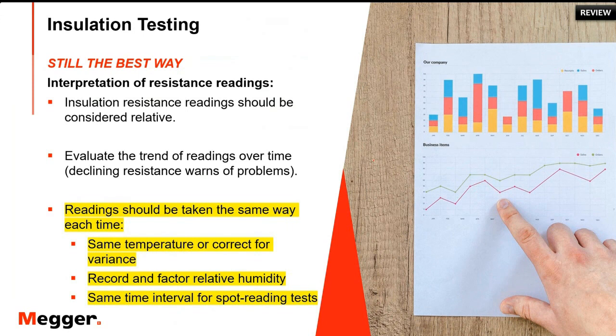So normally, when we talk of insulation resistance, we are correcting it to 40 degrees Celsius. Because remember, resistance has a relation with temperature. Meaning to say, as the temperature changes, the resistance changes as well. So you cannot compare values at different temperatures. You must have a reference temperature. And normally, when we have it corrected, we correct it to 40 degrees Celsius for the insulation resistance testing. So when you do the trending or the comparison, it needs to be at the same temperature.